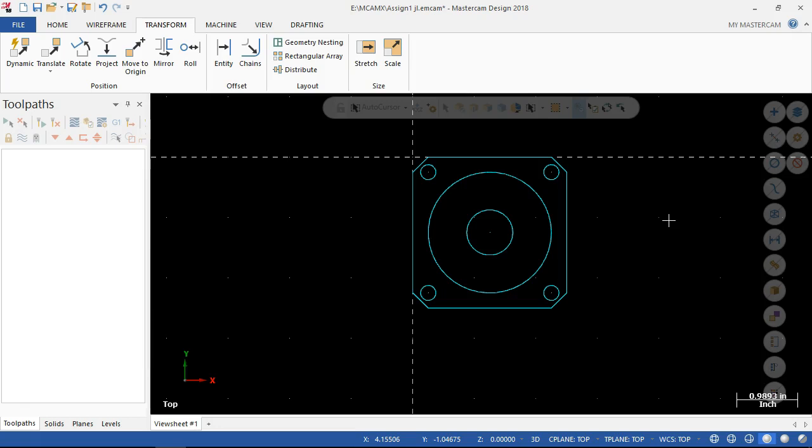And at this point, we're saying that when we go out to the machine, we're going to measure the stock, and if I move in 10 thousandths in Y, go into my control, touch off in X and Y with the edge finder, tell it to take an additional 10 thousandths in Y into the material, take an additional 10 thousandths or so into X, that we're going to be able to run around the outside of this part.